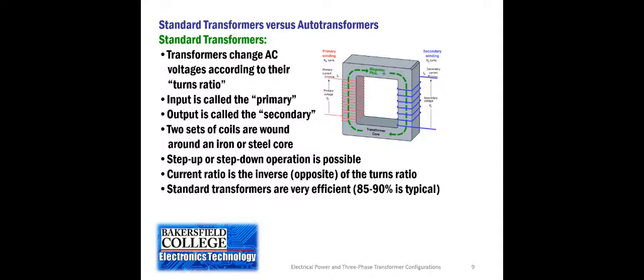What that means is that the power that comes into it, which is what you pay for when you buy electrical power, 85 to 90% of that power will go through the transformer, and you're only going to lose 15%. And then that's great. You'll have a 208 volt three-phase, or a 240 volt. You'll have a loss of power because of the transformer. Now, there's two reasons why a transformer is not 100% efficient.